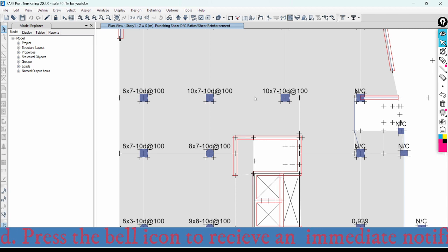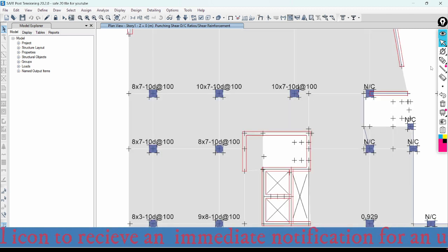Here, digital result here. So here previously when we used the radial arrangements of the stud rail for the design of punching, this one was 10. That is 10 sets of stud rails with 7 studs at every set of stud rails.